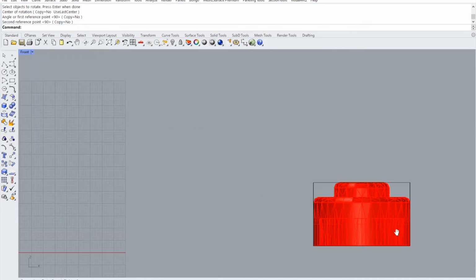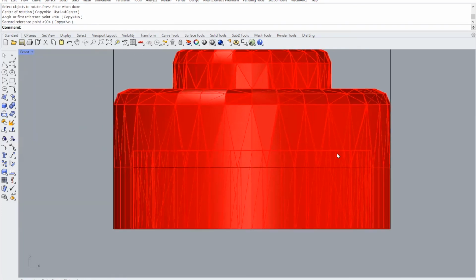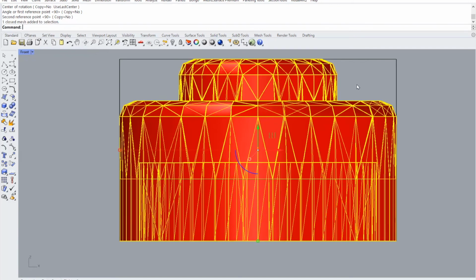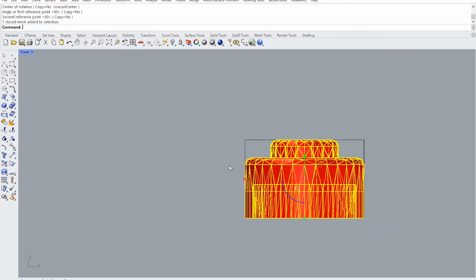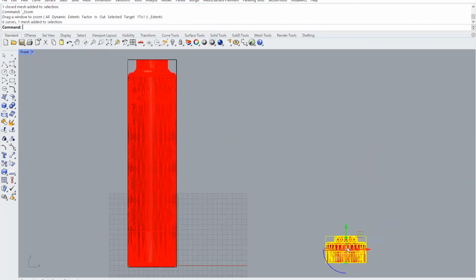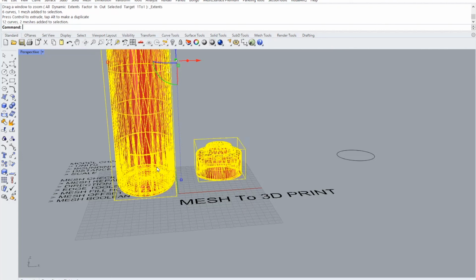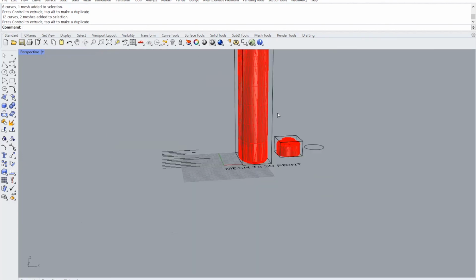The main thing is even though there is an overhanging cap, I will still put support in the 3D printer, and at the same time I'll just remove the support because I would need the external surface to be good when it comes to finishing. So I'll sacrifice the internal surface as the support surface. So I'm just going to select here. Let's go perspective. Let's move this away.